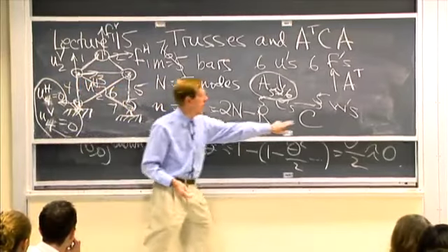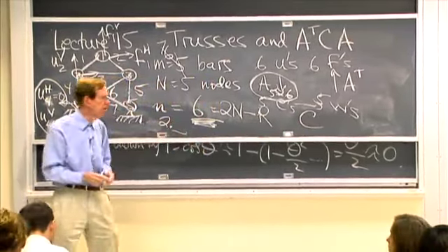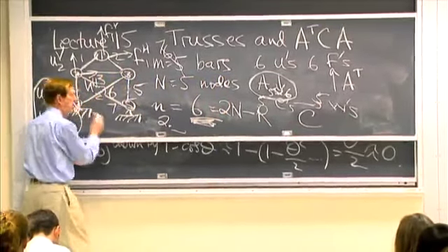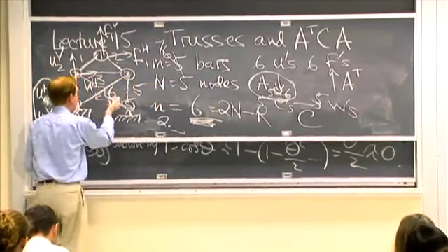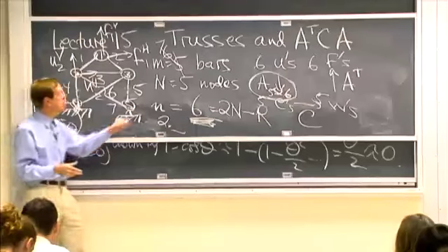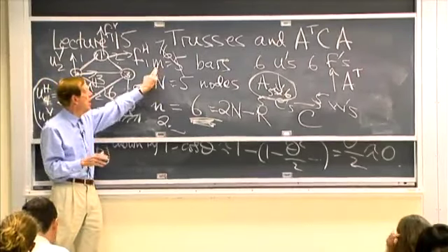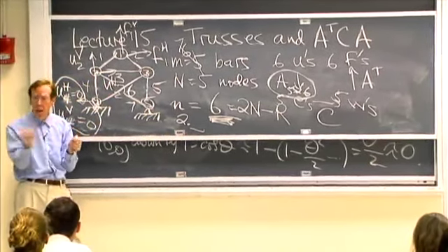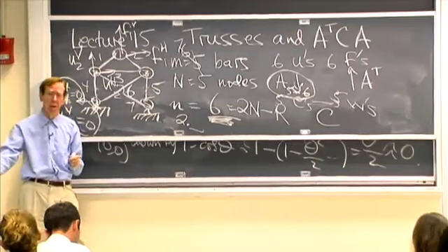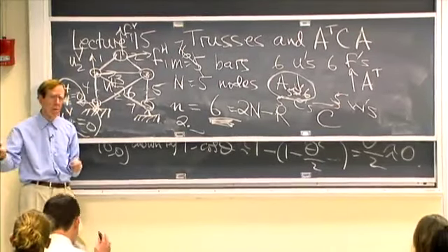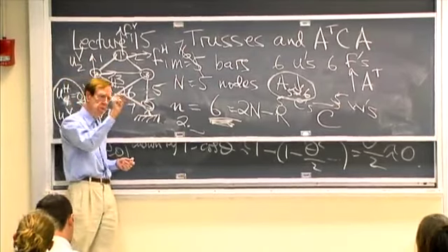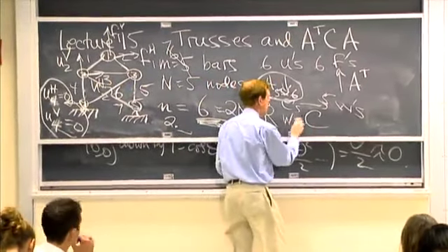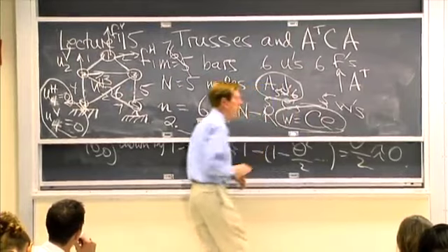Yeah, what's the matrix C? Last second question. What's the matrix C? What size is it? What size is the matrix C for our original problem? Or no. What size is C? If I know these numbers, what size is C? 5 by 5, M by M, right? C is that diagonal matrix. One entry for each bar. C just has a C1, C2, C3, and this W equals CE is just Hooke's law in each bar.